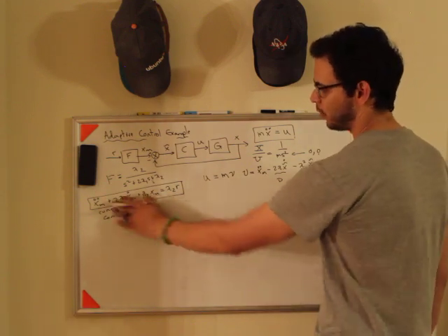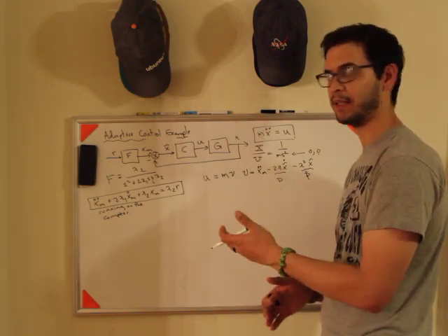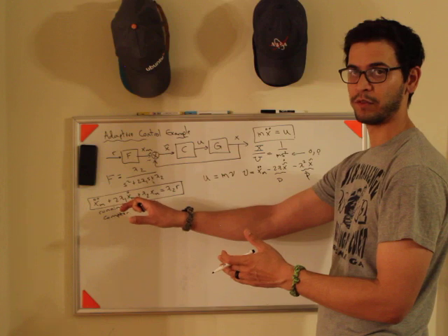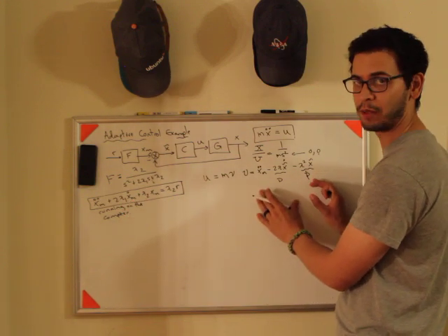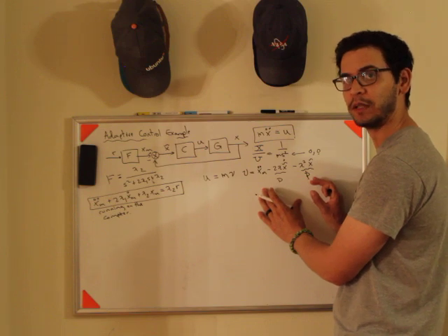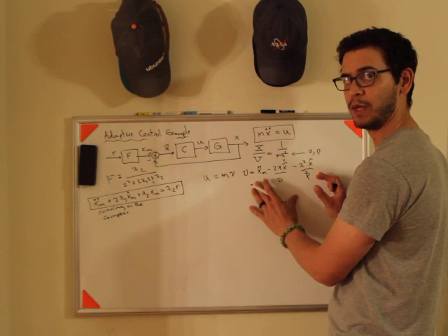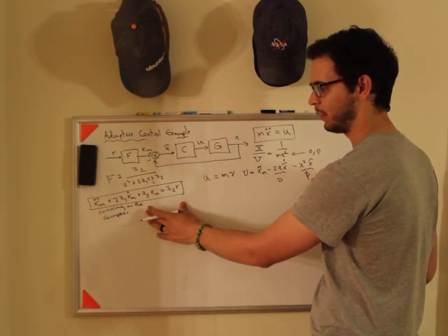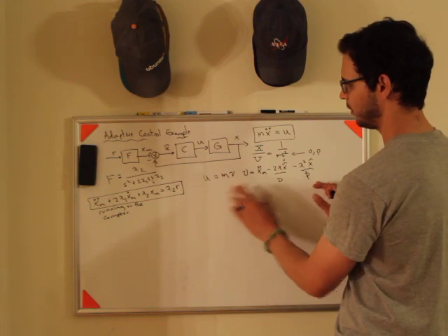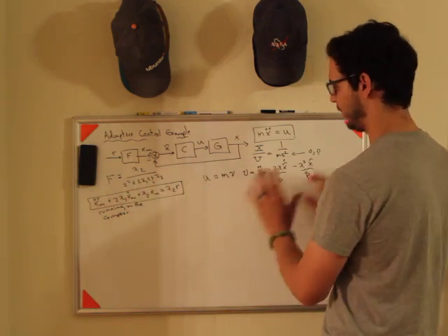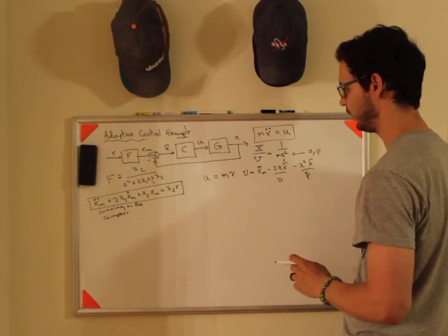Now the thing is you can always tune your reference dynamics, so if you have a step change, you can always make it oscillate just with the model reference dynamics here. Your tracking performance would be critically damped. If you made your tracking performance not critically damped, if you made your reference dynamics oscillate, you would have a lot of oscillations there, and that wouldn't be a good idea. So the better thing to do is to tune your model reference dynamics and then tune your tracking performance separately. Just tune those 2 things separately.